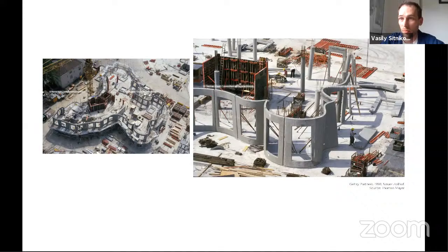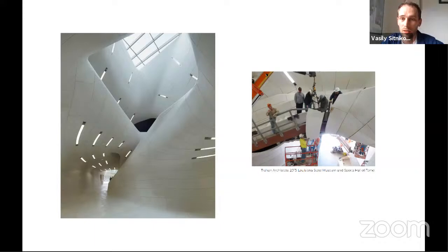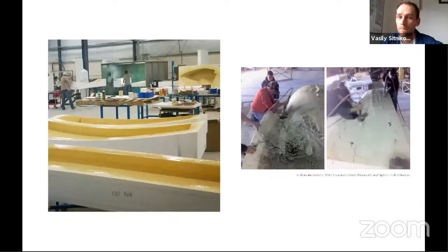So the method became quite popular soon, featured also in the Trahan Architects Louisiana State Museum in Louisiana, where basically a different version of concrete, with similar properties but a different version, called dry cast concrete, has been used for the cladding of the interior surfaces of the hall. You can see that in this case you already need an advanced coating of the formwork, as well as more complex assemblies, as here at the back of the workshop, there is pretty developed volumetric formwork, but still relying on manual crafting and compacting of each of these elements manually in the formwork.